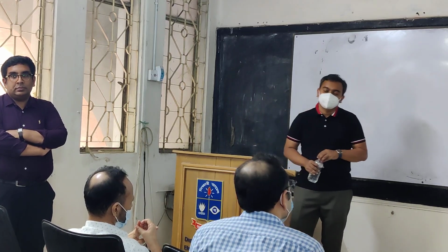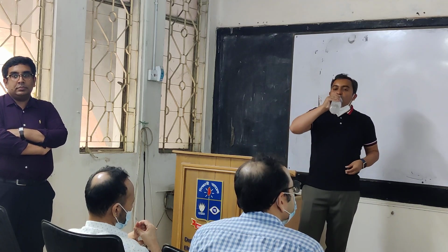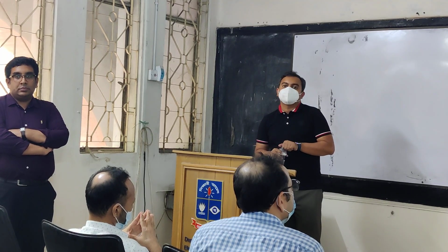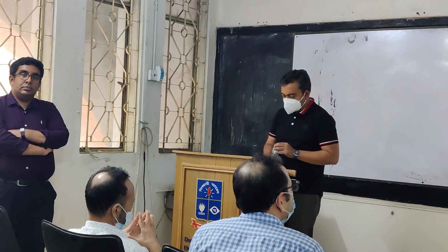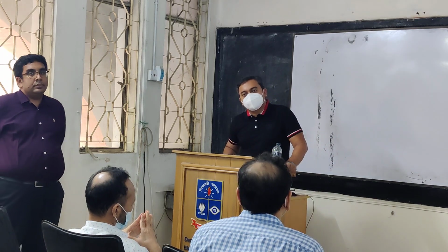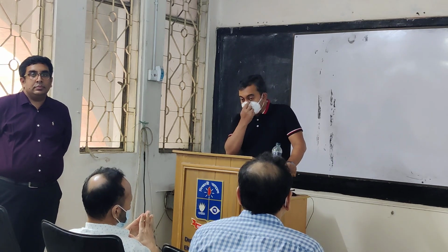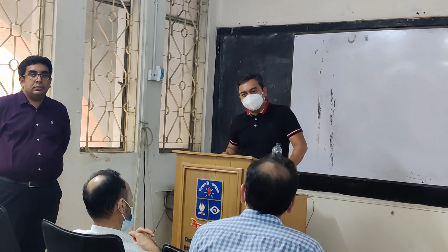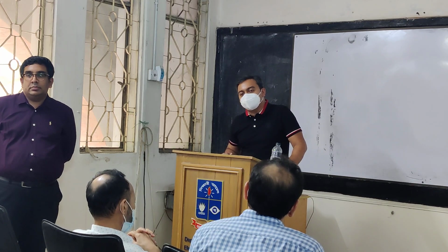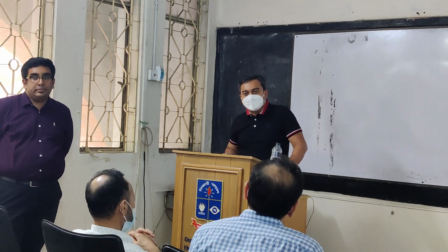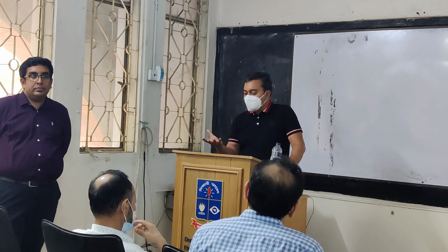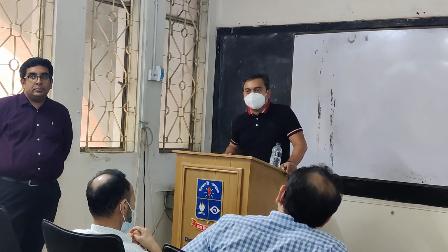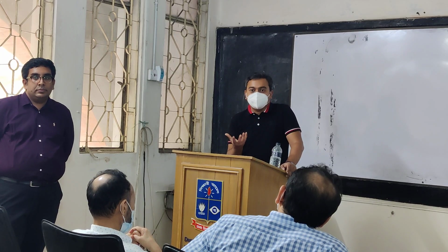Thanks. So I had another question, like here you use hafnium dioxide. What's the availability of such materials for greater scaling? Silicon dioxide is found everywhere, but what is the scope for such materials? Hafnium dioxide is actually quite available. The biggest thing is you are using an extremely low amount of hafnium, because you are using 1.8 nanometers. Very little. So even if you are using millions of wafers, 1.8 nanometers still amounts to little. The importance of silicon is because your handle is silicon. That thing is thick. So if that was expensive, then we would have trouble. Which is the trouble for, let's say, gallium nitride. Gallium is very expensive, so you cannot have that handle.